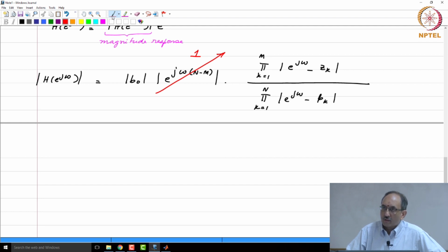You plot the log magnitude, and typically the scale is what is called the dB scale. So, why is it that you are going to plot the frequency response in log magnitude? Why don't you see this plotted on the linear scale? Typically you are told that if you have a large range to cover, you will use the log scale.